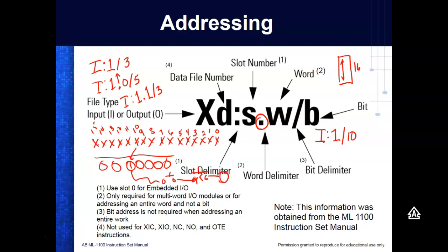Well, it is a memory bit. So what happens is when the PLC reads the inputs, it puts them into a memory file, to a bit in the PLC's memory. So the program does not read the inputs directly. It reads the input files.